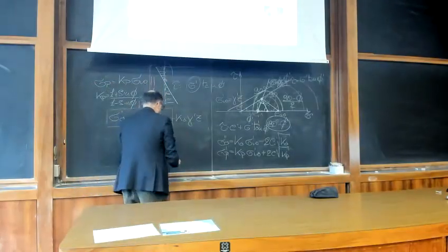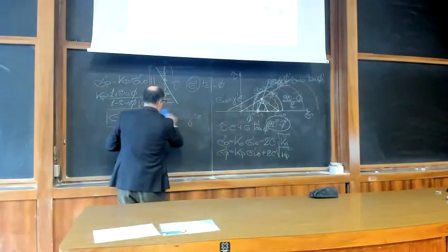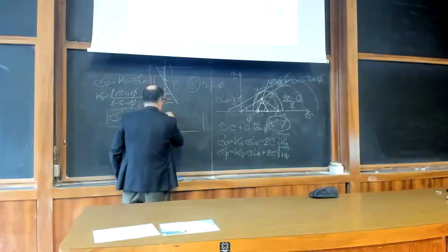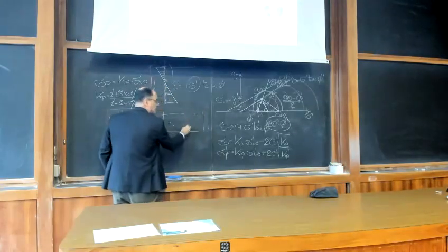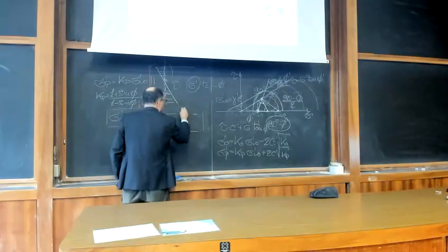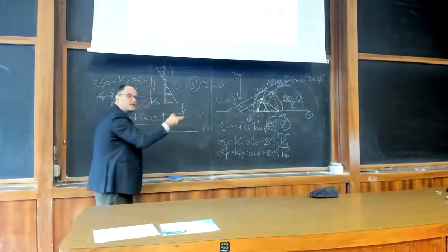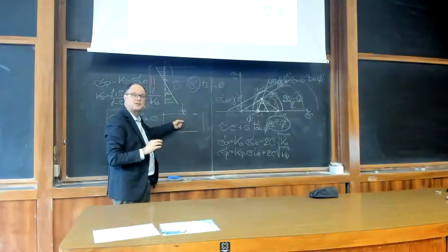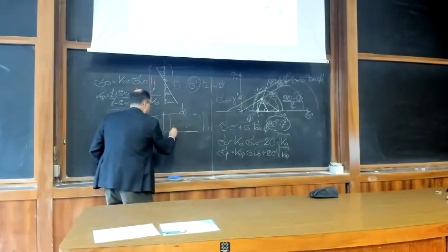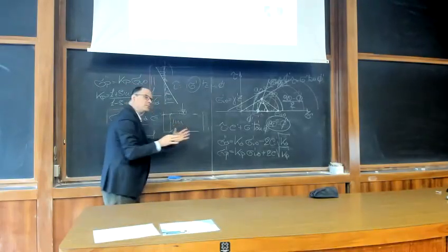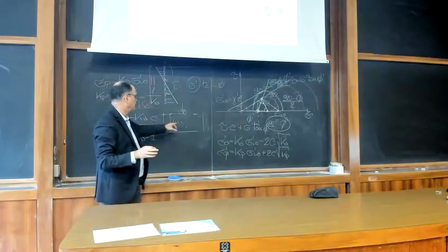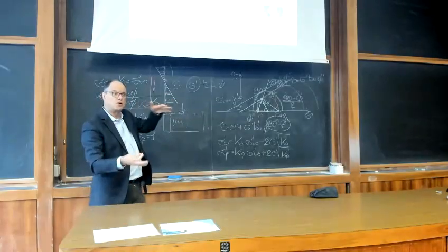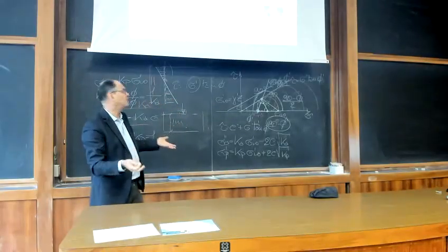If I build a caisson like this, and I fill this caisson with sand, then I put a small footing here, I can load it, and I can measure the settlement. This is like a small-scale foundation. But the stress field inside here, if this is 1 meter, you can't do a model which is much larger than 1 meter. The stress field is not the same as you have at 10 meters or 100 meters or whatever. The stress field that is in reality.